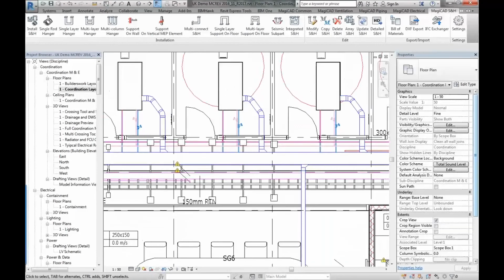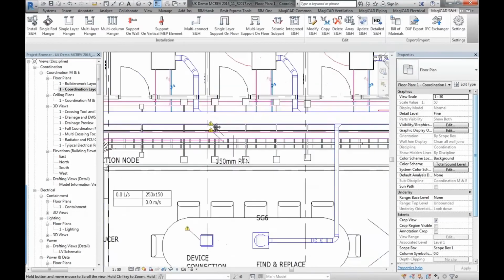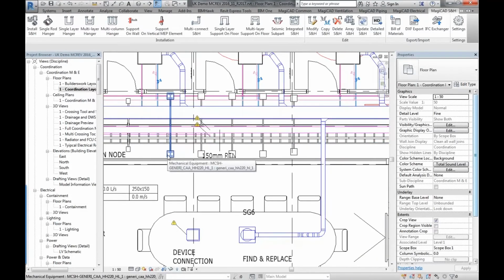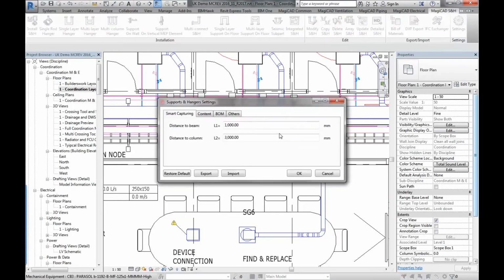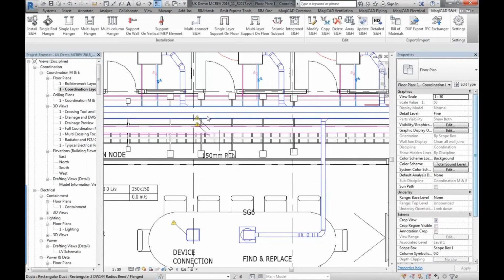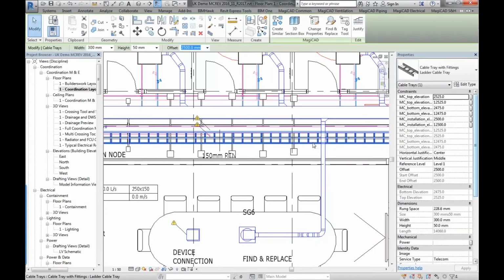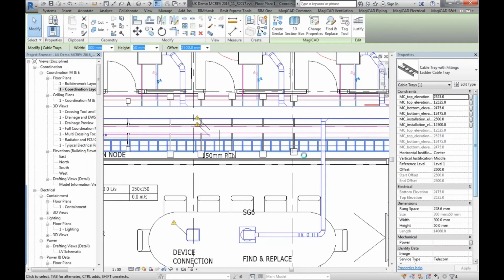One thing that's interesting to note is that if you've selected the hanger to be linked to the objects, which you normally do to create them, in settings here you can see that it has update automatically. You can turn it on and off. So if I now nudge some cable tray down like that, what you'll find is the hangers will move with that cable tray as well automatically. But you can see it might be quite heavy on resource.